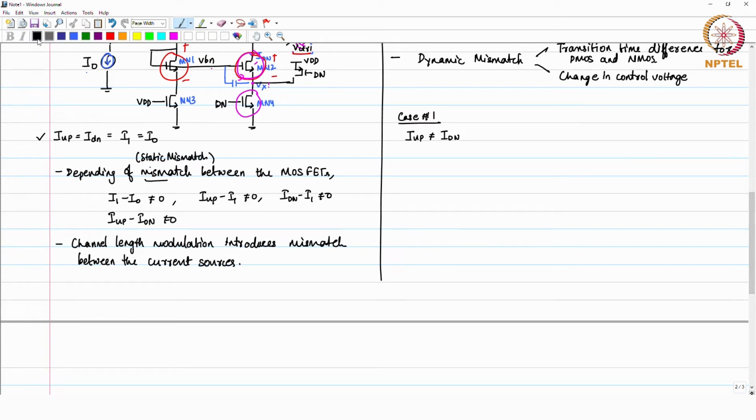So, when this mismatch exists, what will happen is, you have your PFD which gives you the up, up bar and down signals to control the charge pump. You have these signals R and V. V is the feedback signal, R is the reference signal. Ideally in a steady state you should have R and V aligned.